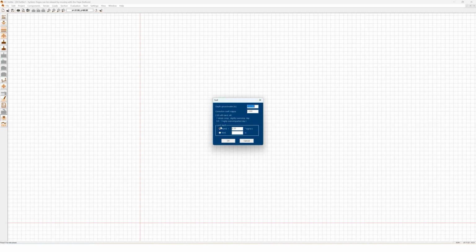Then we have the limit depth here. For the determination we use the constraint modulus method. So we divide the stress by the stiffness modulus, and this results in a settlement. And then we add up the settlement over the depth until the load stress is less than 20% of the surcharge stress.